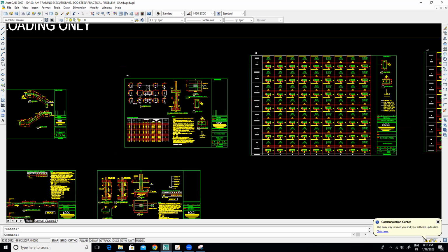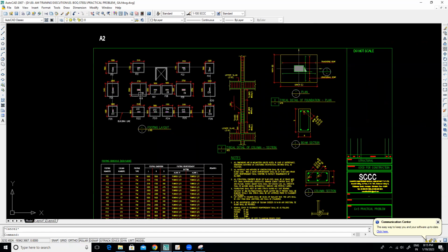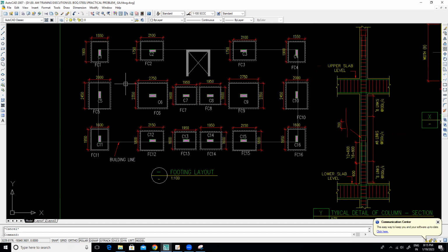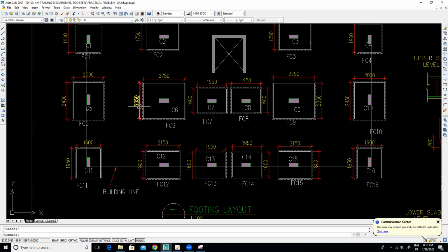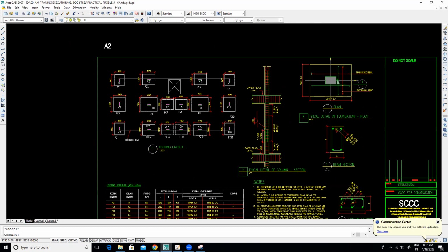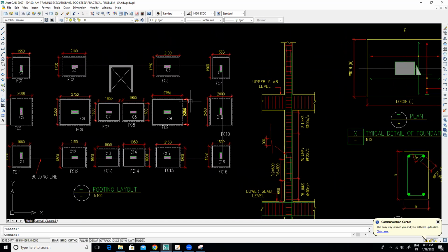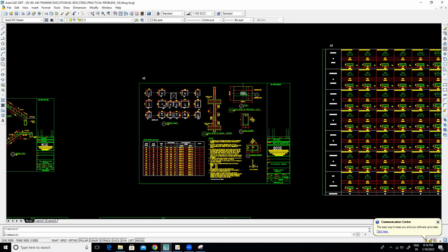So site people or construction team will not bother what you have done in the software or in the calculation office. They will not check. They will only bother whether the dimension is correct, can it be constructible, and is it correct from construction point of view. So the dimensioning of the drawing is very much important. The level of the drawing or level of the section.